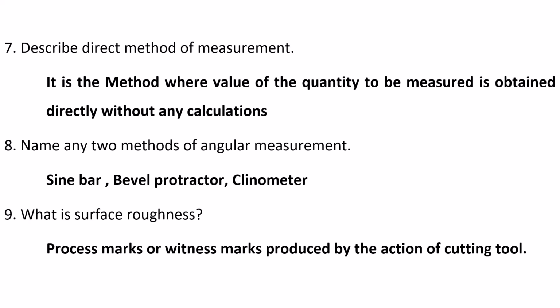Name any two methods of angular measurements. Sine bar, bevel protractor, clinometer, etc. are the equipment used for angular measurements. What is surface roughness? Process marks or witness marks produced by the action of cutting tool, that is called the surface roughness.